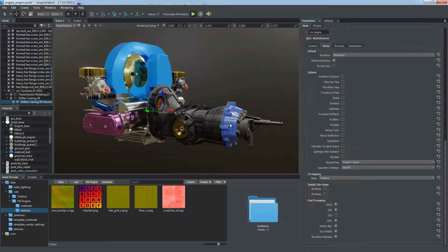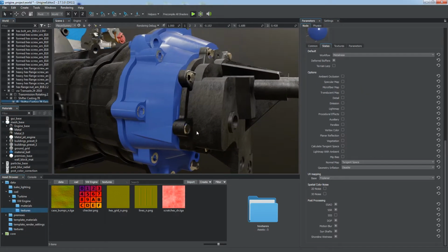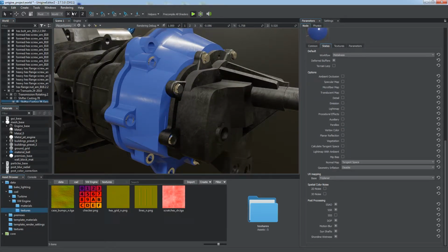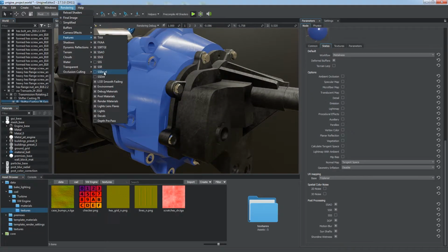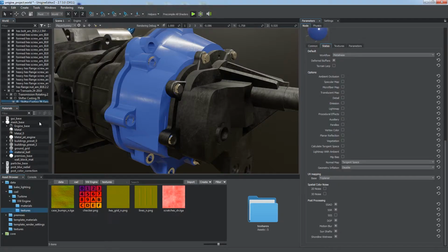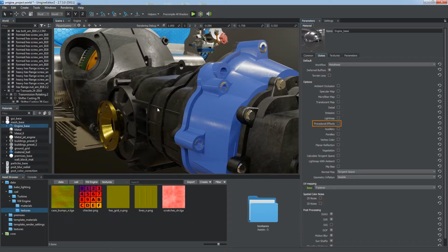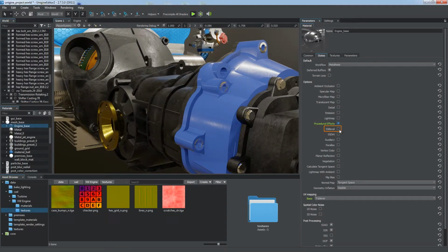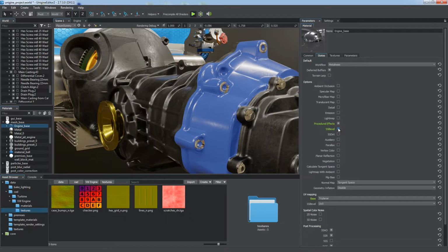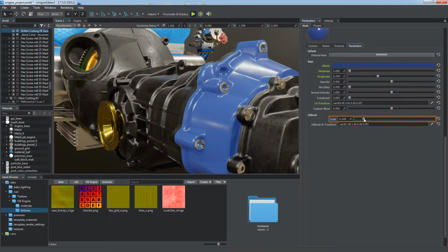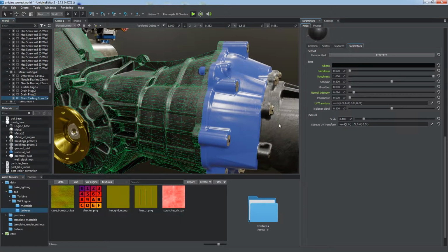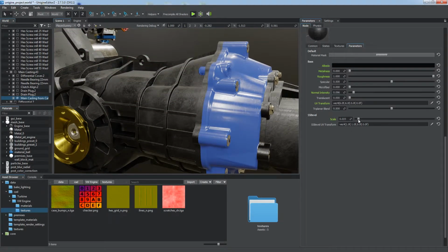The Bevel effect is procedural, so we can easily use it for a CAD model. To activate it, just enable the Bevel feature in the rendering menu section and turn on procedural effects in the material states to activate. Now all the edges of the engine are visually beveled and have nice specular highlights, which make details more prominent. You can adjust the intensity for each material via the scale parameter to make the blue case look smoother and the edges of the black part to look sharper.